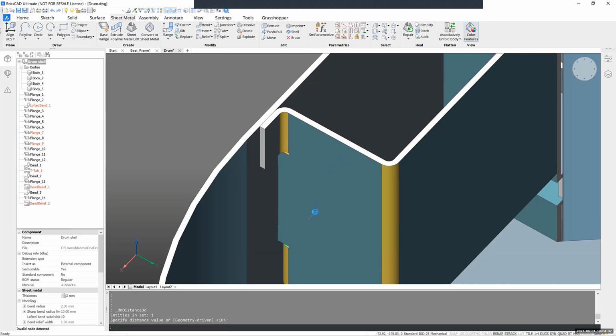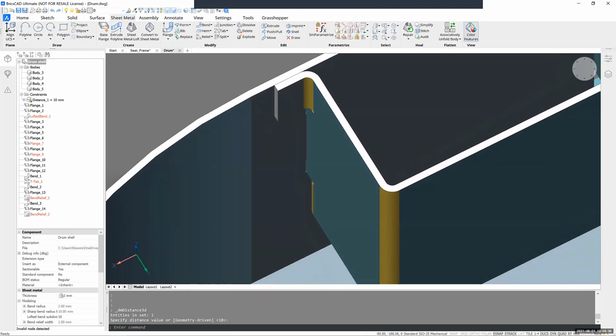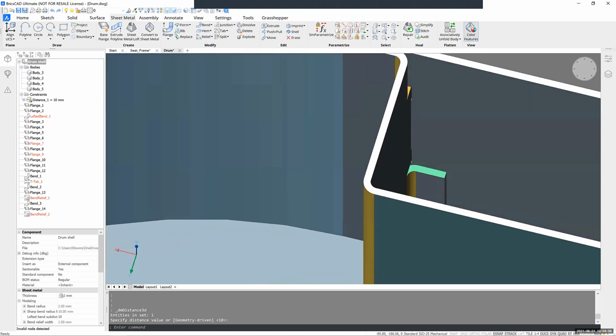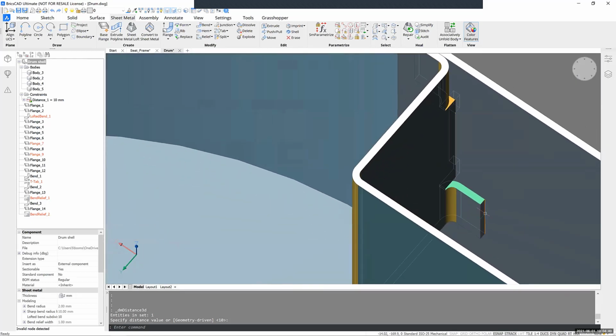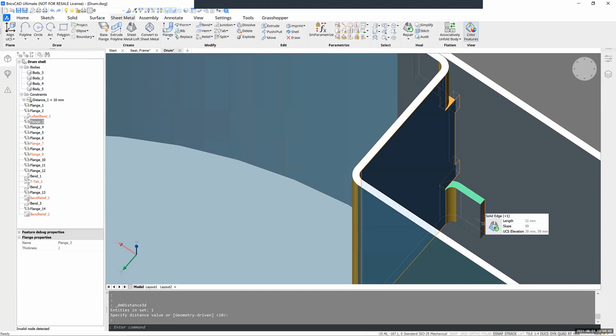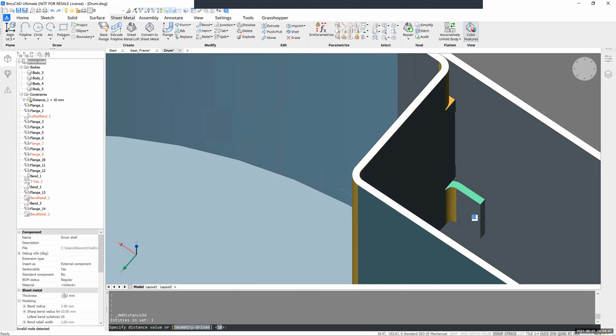And then I select that, and I do the same for the inner one, because the inner one would have the same problem otherwise, that it doesn't stay the same length like I want to. So I select these two faces. Again, a distance constraint. And before I also did this, but just accept the default 10 by pressing enter. Then it will also always stay 10.